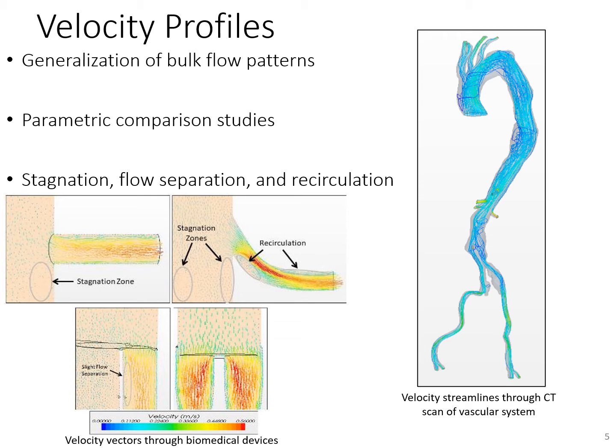These images can provide a quantitative analysis of each system, allowing the user to make general overall observations of the fluid flow patterns and begin investigating design changes that could optimize these flow trends. In the examples provided here, the left images show a biomedical comparison that was made between 4 different thoracoabdominal aneurysm repair devices. These qualitative results were able to show where stagnation, flow separation, and recirculation of blood flow may be located due to implementation of each of these devices, which can lead to issues with clot formation and delayed nutrient supply to arteries, among other things.